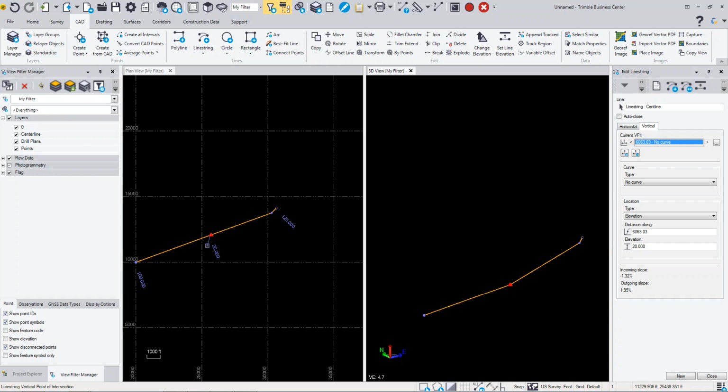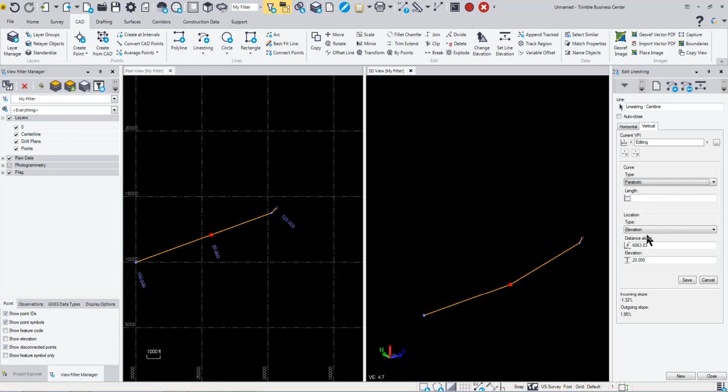Now you can also put in a vertical curve. So if I wanted to have a vertical curve through here, I could do something like this with a 2,000 foot length of curve, and now I put a vertical curve along that 3D polyline. So basically, if I was drawing this as a center line, I could draw it as a line string, but putting in curve, not only horizontal geometry but curve geometry.